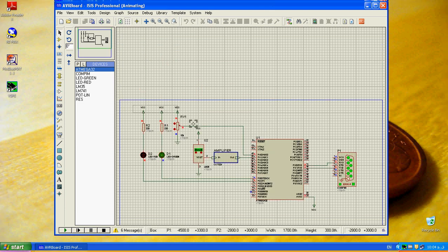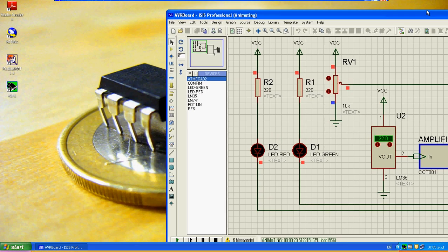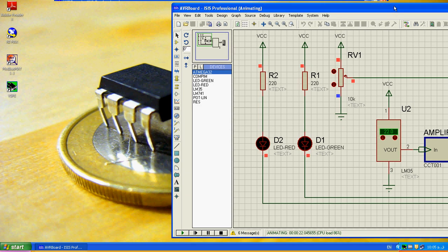After the simulation starts, we focus only on the inputs. As I described, D1 is periodically turned off and on every 1 second, but consider that the simulation is not real time, so the timing may actually differ from a physical device. The potentiometer can be increased and decreased, and the temperature can be increased and decreased accordingly. D2 is also controlled by the Modbus master that we want to implement in the LabVIEW environment. Okay, this is our Modbus slave part.